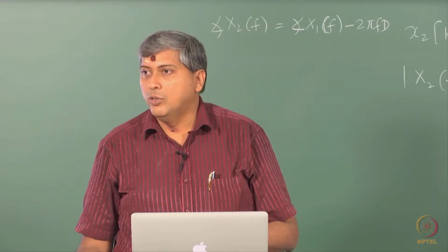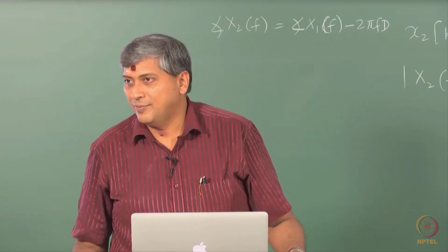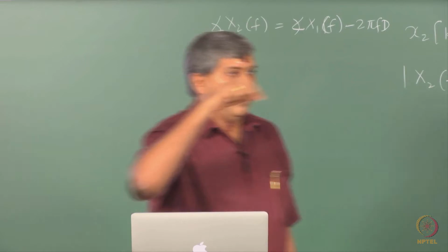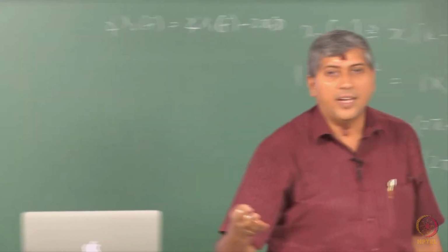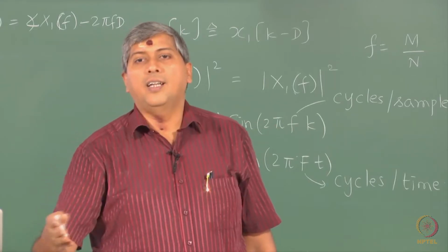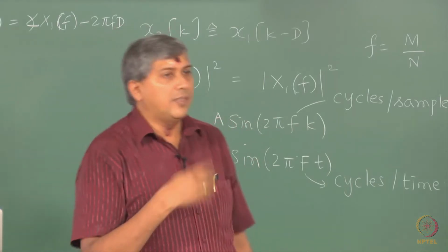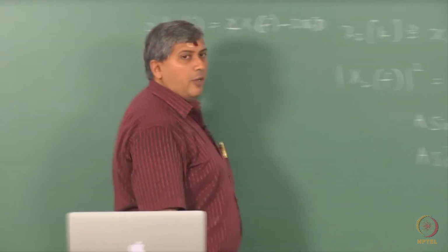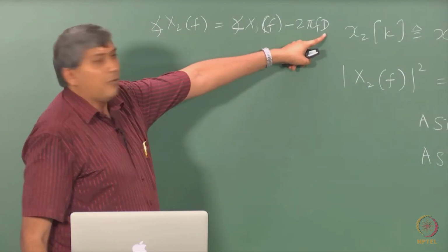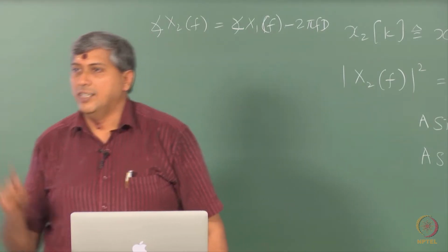Then all I need to do is look at the phase difference between the input and output, and of course, I can just use a single sine wave of some known frequency. Since I know f, and I know the phase difference of the output, from there I can figure out what d, the delay, is.